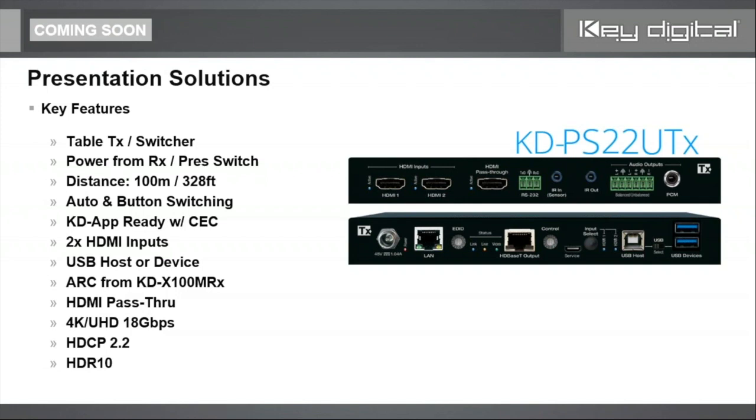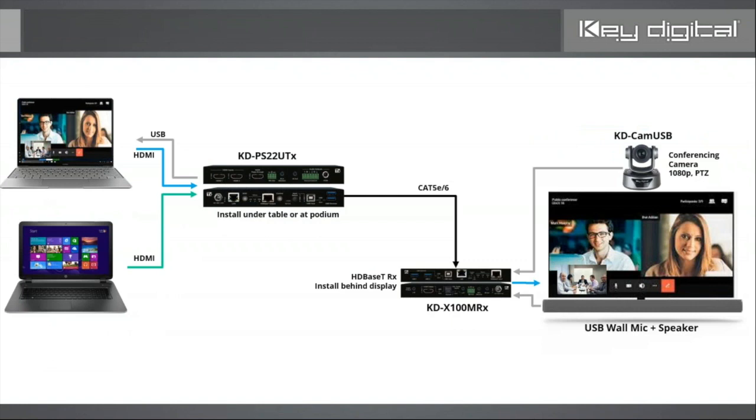So many times people ask us, do you have an extender, an HDBaseT extender that supports ARC? And this is our first product which does support ARC. A lot of people don't understand that ARC was not part of the HDBaseT specification until later stages and later updates to the HDBaseT chips, and they are very expensive, unfortunately. That's why you don't see audio return channel in many products in the industry. There's a second HDMI output here so that you can connect to a local monitor. Let's look at some of these application examples.